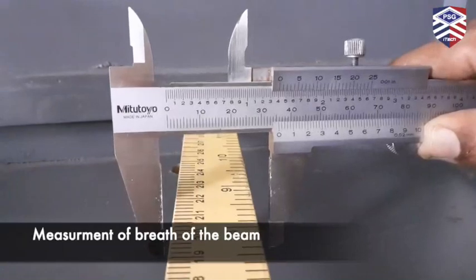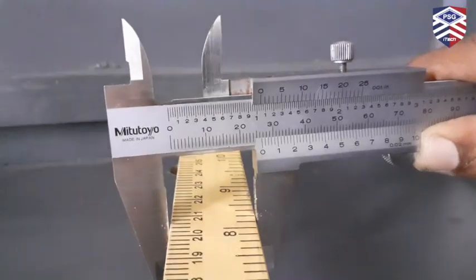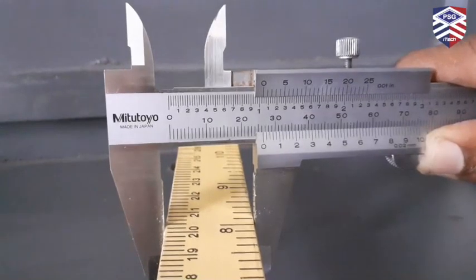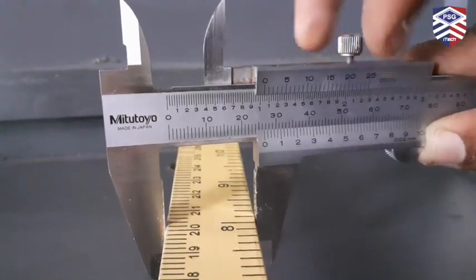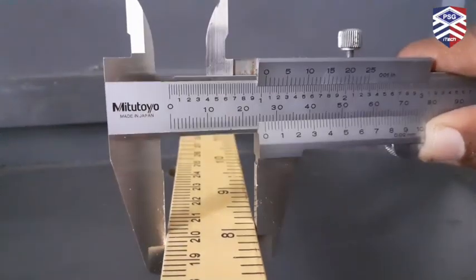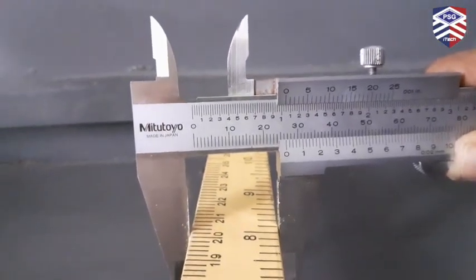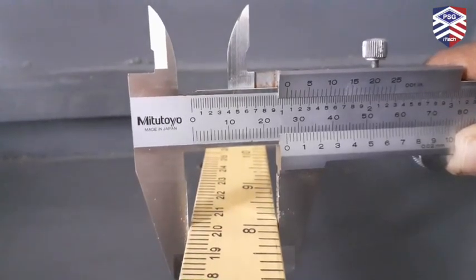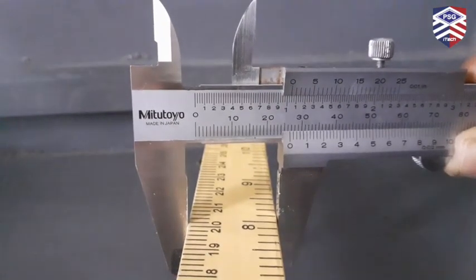Now let us take the vernier close to the breadth of the scale and move the sliding screw such that the fixed end of the jaw gets hold of the scale. Once it has been fixed, we will tighten the screw such that the lower jaws will not move further, so that we can take the readings carefully. In this case, the main scale reading here has crossed the 26th division. How do we tell that? Let us see in detail.